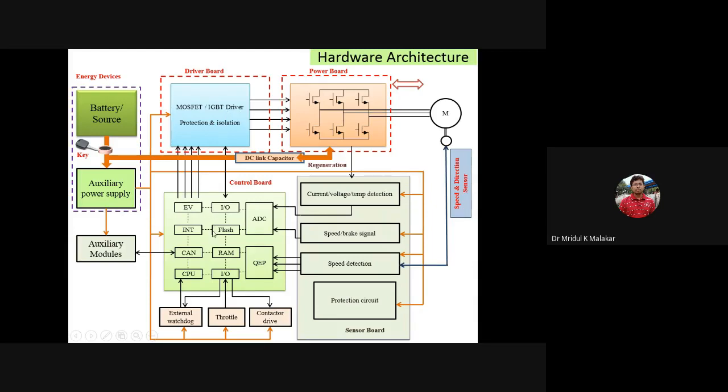See that it has flash, ADC, PWM module, IO, RAM, CAN. So the total CPU is there. The sensors you are taking, the processor will take a 3.3 volt level or a maximum 5 volt level, and a milliampere current rating. For the total signals and sensors, you have to take a milliampere rating, maximum 500 milliampere suppose, and the voltage is 3.3 to 5 volt system.